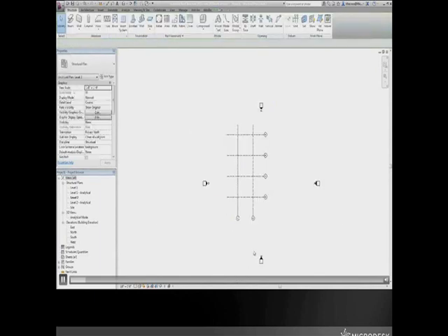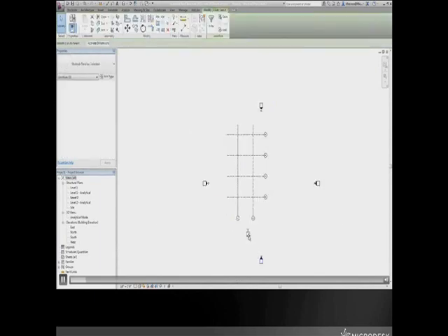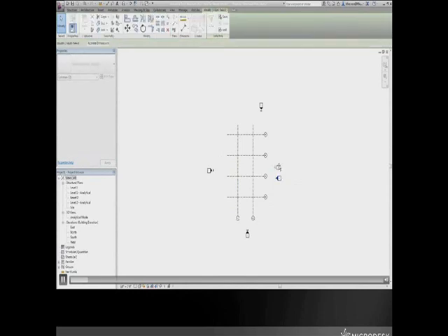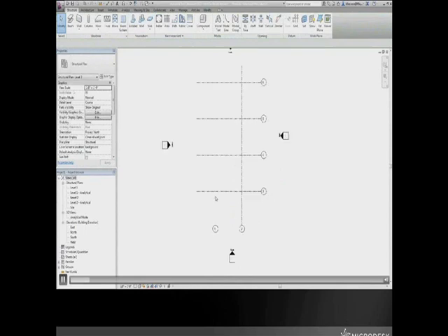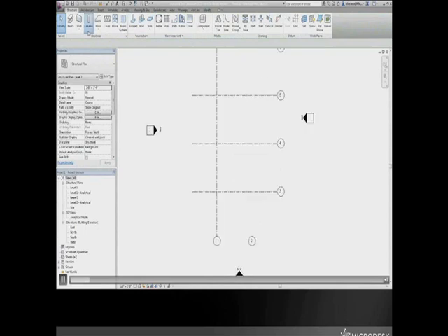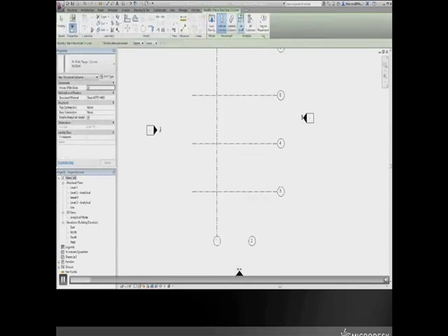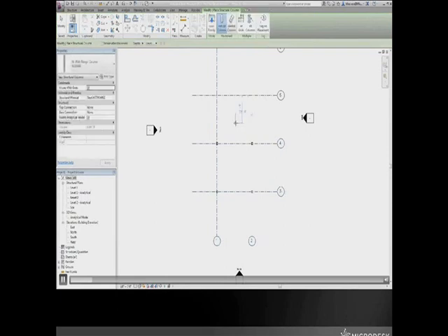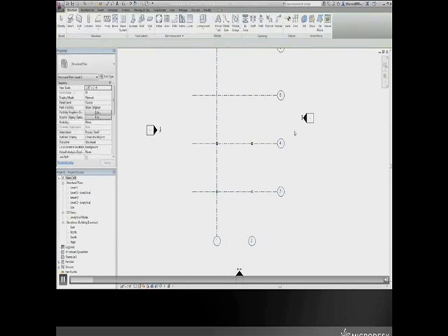Now I'm going to start to, again, like before, look at our elevation marks around our structure. And I'm going to start to create a steel structure, steel frame, a box. So I'm going to start out by inserting columns. I'm going to insert them at selected grids here. So I have 4 columns. Now I'm going to connect them with beams to make a box.